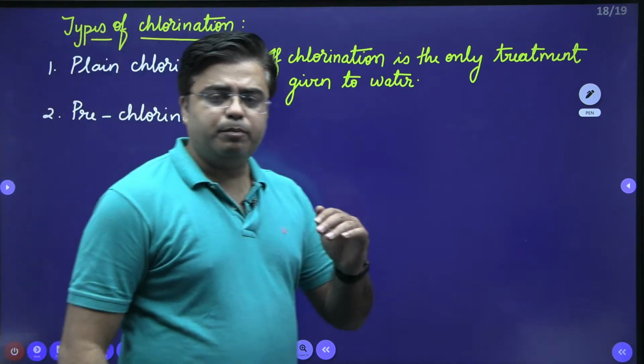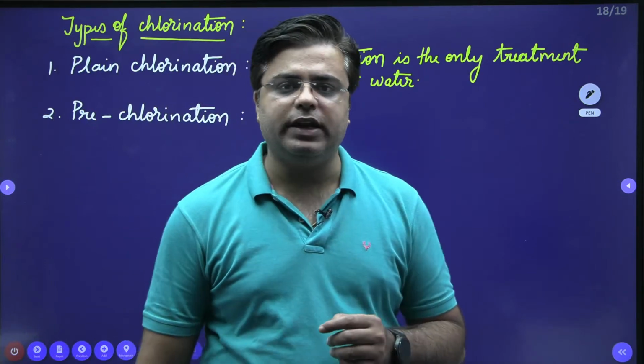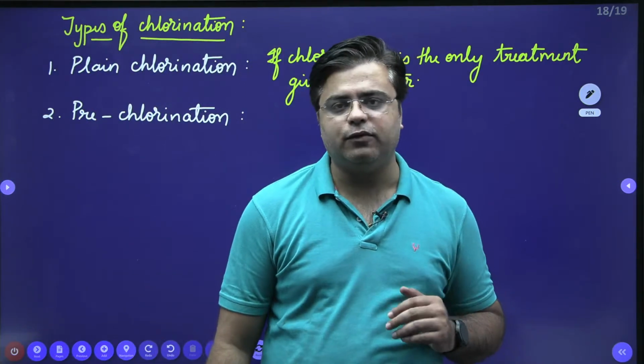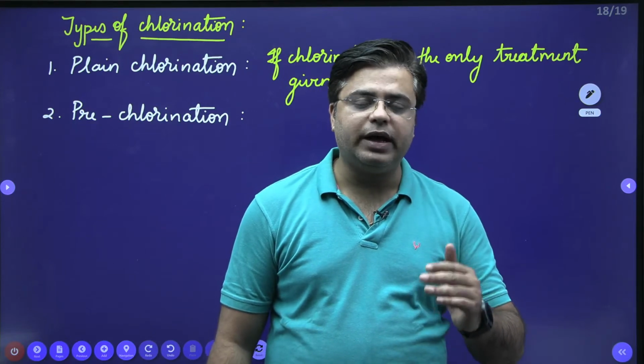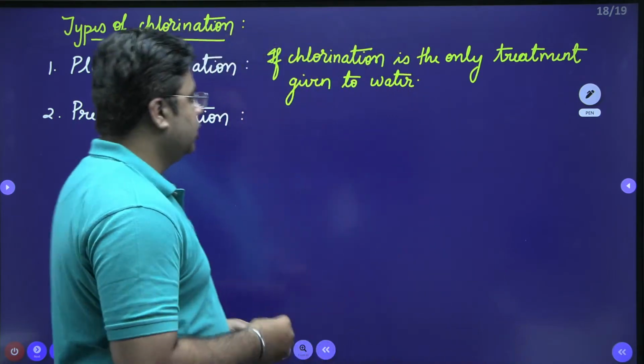So, before coagulation and flocculation or along with coagulation and flocculation, if you do chlorination, it is known as pre-chlorination.